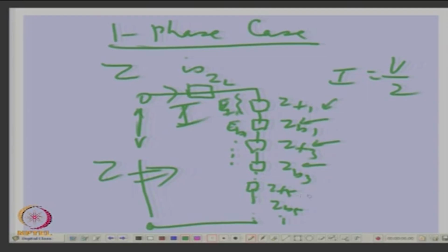So, we have to take positive sequence impedance separately, negative sequence impedance separately, zero sequence impedance separately, or you can go through the actual rotating field approach. So, VA, VB, VC will be equal to the impedance matrix ZAA, ZAB, ZBC, they will consist of these impedances. Okay. In 3 phase you can calculate directly or indirectly through the transformation to symmetrical components.